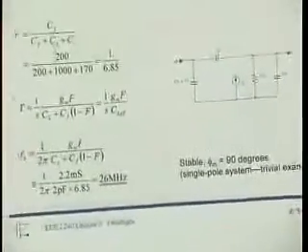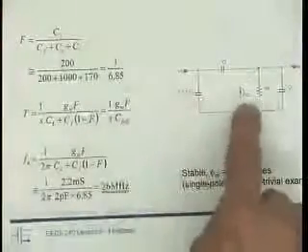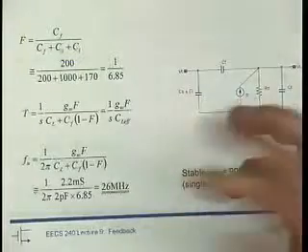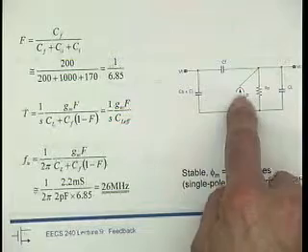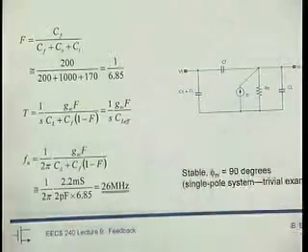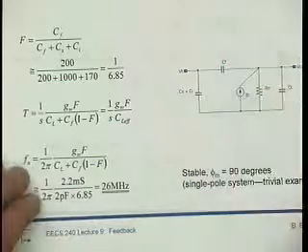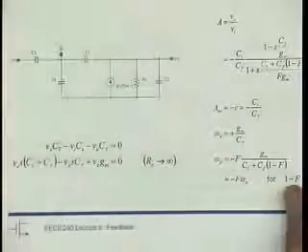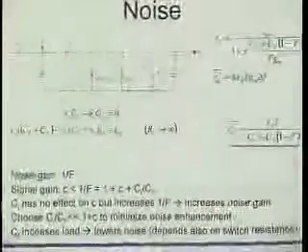I have one more example here, that's really for this return ratio analysis. Doing the same thing by hand, where again I replace the transconductor here. I draw the small signal model, and I replace the transconductor with, say, a test current source, and then measure the voltage that develops, I need to open the loop and measure the voltage. So I'll let you go over this yourself.